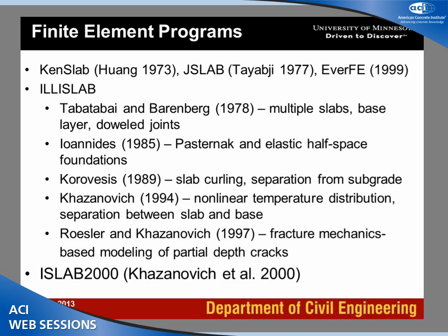There are several finite element programs which were developed specifically for the analysis of concrete pavements. I will just mention a few of them: KENSLABS, JSLAB, EverFE. But the most popular finite element program was ILLI-SLAB, and there were several versions of this program which addressed various limitations of the Westergaard theory step by step, and eventually that program was replaced with a computer program, ISLAB2000, which was used in the development of the latest mechanistic-empirical pavement design guide.